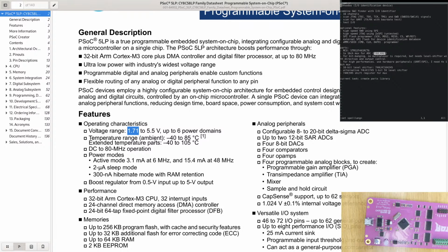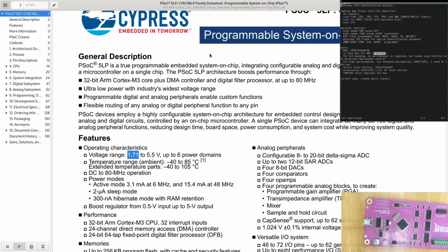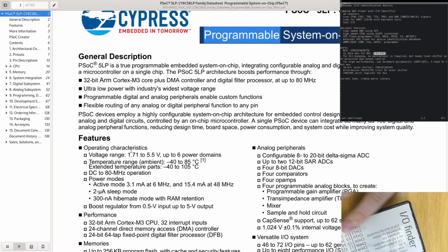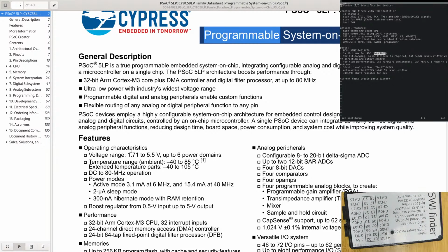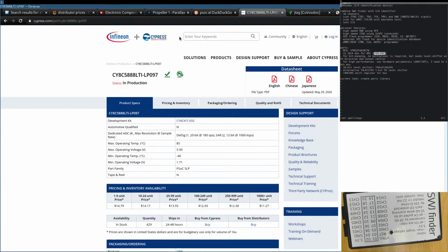It can do matrix switching, and you can program analog multiplexers inside. So I could use this chip just for multiplexing, and I could somehow program it over serial so that it does multiplexing and which pin goes to what, because it also is capable of doing analog multiplexing. But let's have a look at the chips.